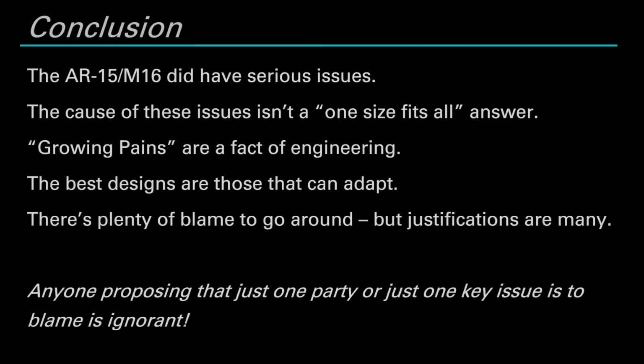And so the introduction of chrome lining in conjunction with the improvement of those instructions helped the rifles get to the point that they could perform in the way they needed to without being overly susceptible to the humid environment and without having to be overly reliant on soldiers sticking to their cleaning and maintenance regimens. And so these two issues are very much intertwined and, while still connected to, distinct of the powder change and the updates to the buffer.